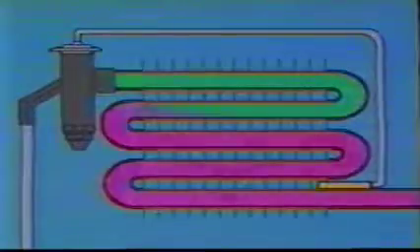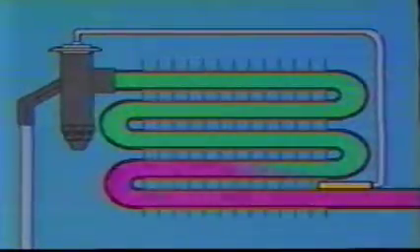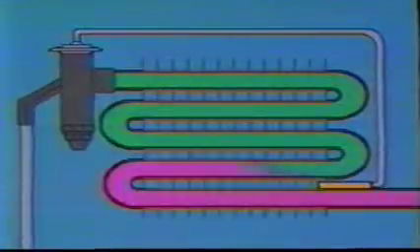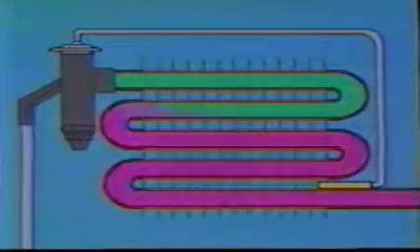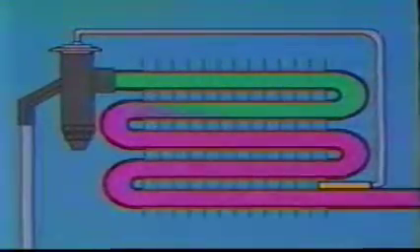Some hunting is inherent in all control systems. Because of time lag in the controller in both receiving inputs and in the system responding to the new conditions, the potential for hunting is always present. The effects of hunting can be reduced but never totally eliminated. A TEV that is hunting will cause excessive swings in the superheat level as well as swings in suction pressure.